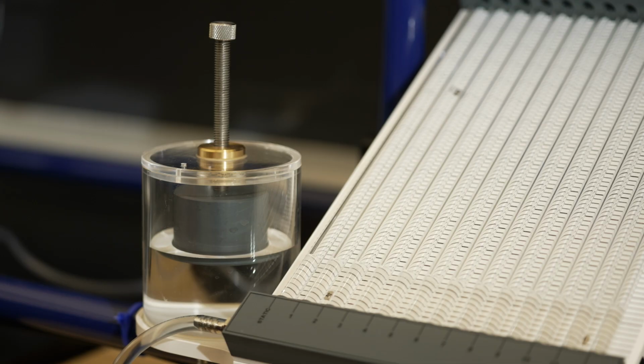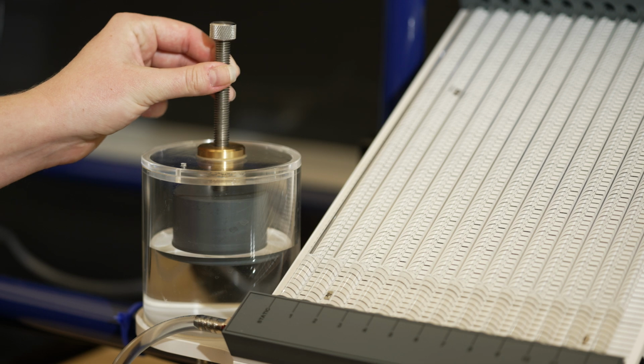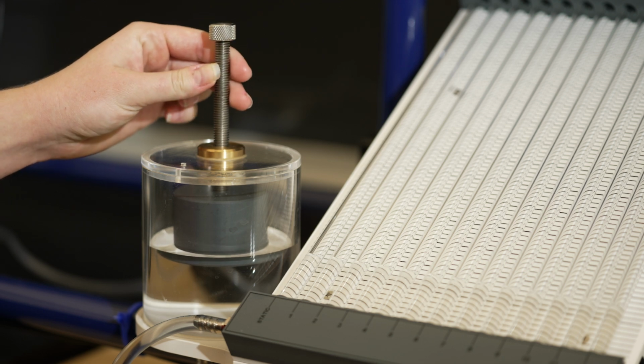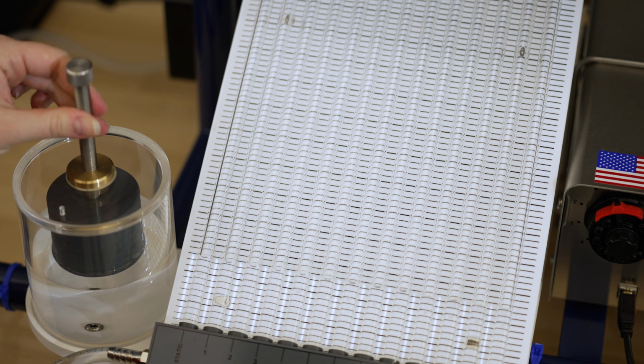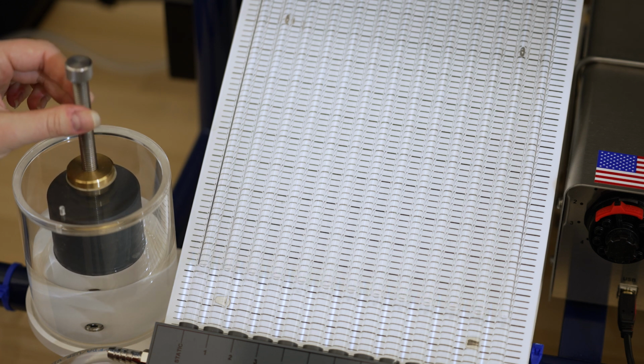Before any measurement, set the tube water levels to a defined value by twisting the screw on the reservoir. A value of 20 millimeters typically works for all experiments. The reading displayed on the incline manometer accounts for the incline angle. No trigonometric conversion is needed to document the height of the reading.